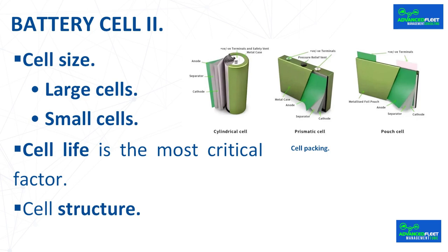Large cells. It is the simplest way to manufacture a pack, and it is used by the vast majority of hybrid and electric vehicle manufacturers. At a constructive level, the number of connections and the complexity of all systems, such as the battery management system (BMS) and cooling, is much lower. In the event of a serious failure of one of our cells or modules, the entire pack seriously suffers in power and capacity, or may stop working altogether. The larger and more capable the battery cells used, the less flexible the capacity of our pack is, and the more sensitive it is to failure, but its construction is also simpler and cheaper.